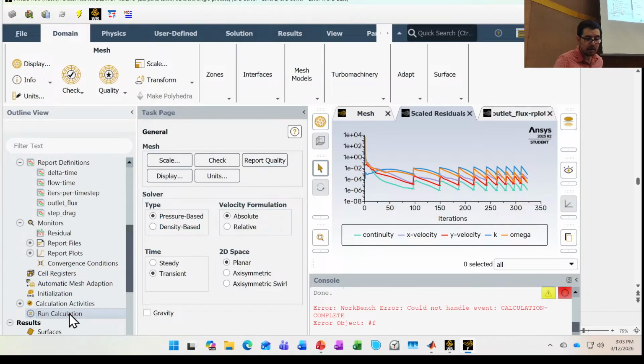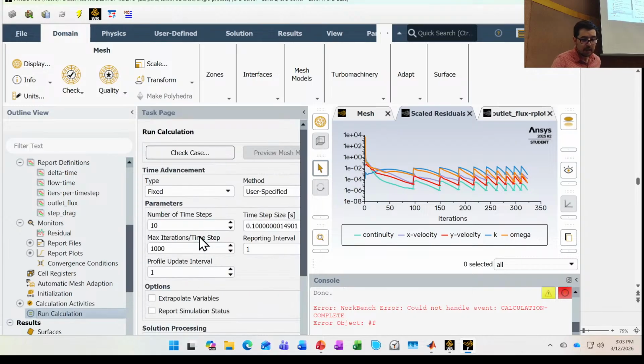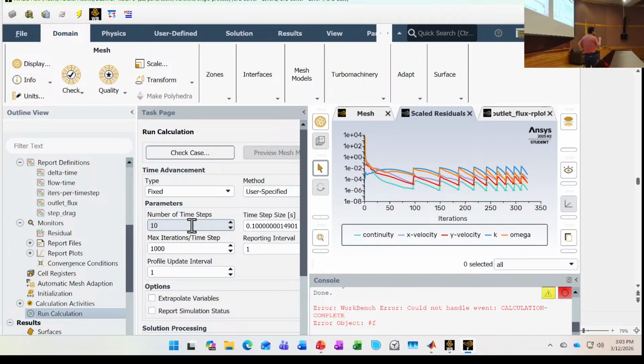Well, I wouldn't expect you to remember. We said we were going to do 10 time steps. This is a transient simulation. We're running it for 1 second, and we're doing 0.1 second intervals. That's what we're recording. That's like the I record in the finite difference method that we were using, right? But what do we do in between the I records? We play with the time step. Well, sometimes we play with the time step, right? We get trying smaller and smaller time steps.